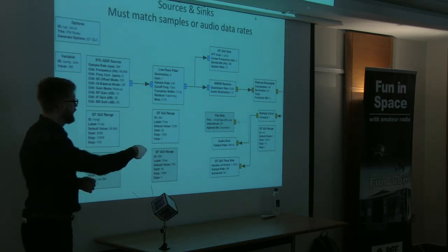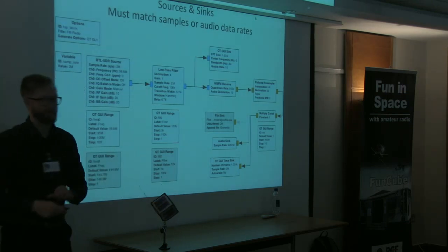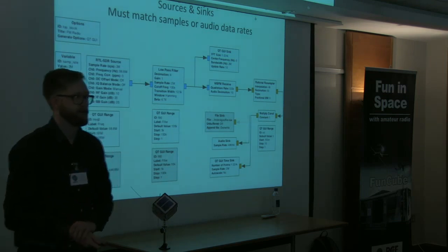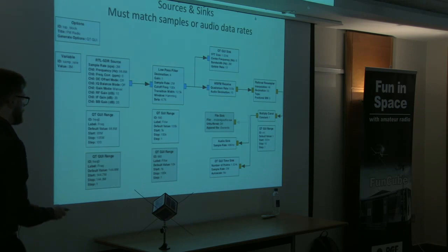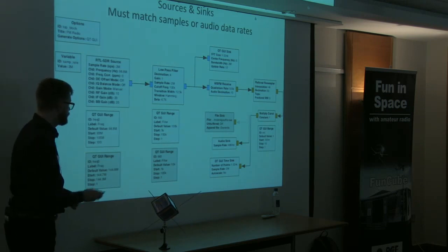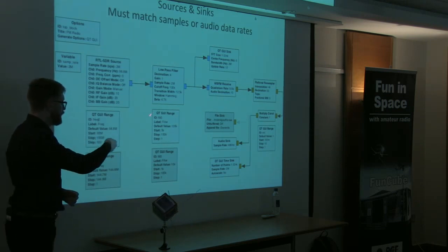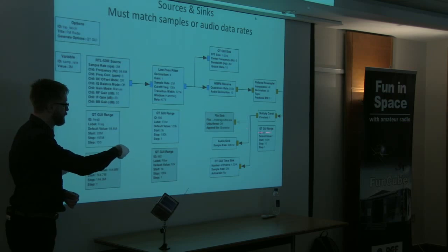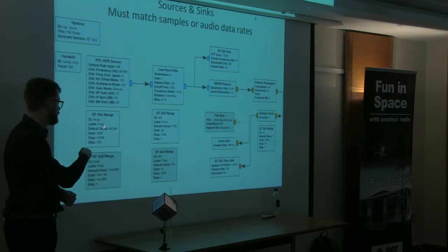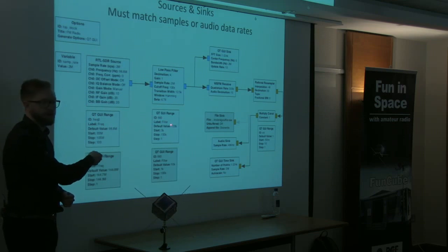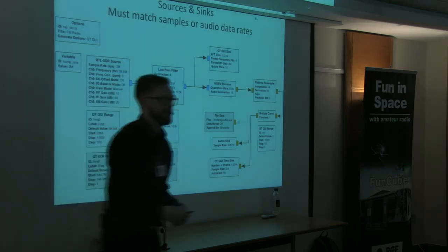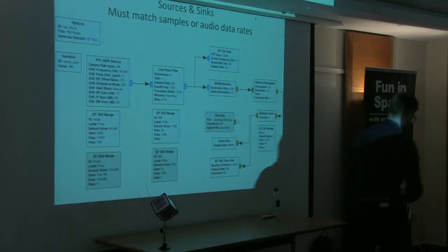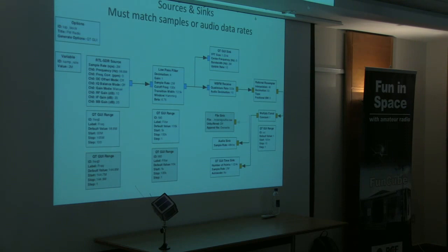And what I've then done is I've then just dragged a block over called AudioSink. All these libraries, they're all built there for you. It allows you to then go ahead and drag in these things and use them. And I've used a couple of these range things just so that I can then play around with the menus. Here I've got my center frequency that I might want to be looking at. I want to then tell them how big a range that I want my filter to be. And then I've just got a volume switch which then multiplies and amplifies that signal. So let's go ahead and try that one.